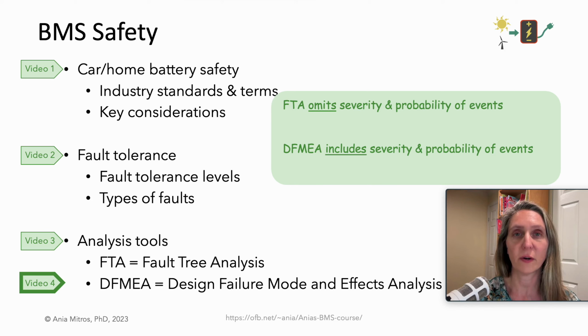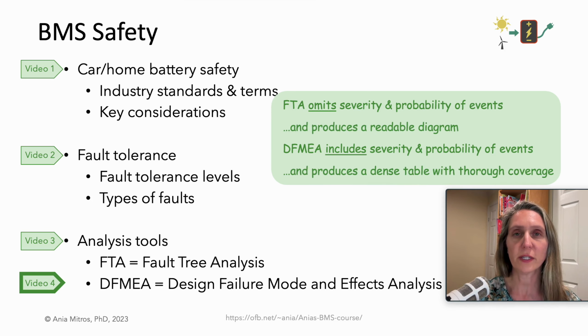Neither tool is better or worse than the other. They are useful in different ways. Fault trees produce a more readable output, which is valuable for design. DFMEA provides greater coverage, which is valuable as a final check.